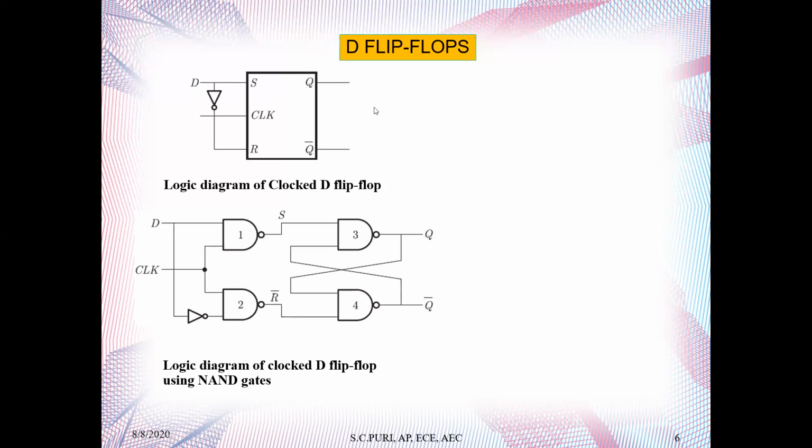So what is the advantage? Delay. The advantage is the delay. Using this configuration, we can introduce a timing delay, and this timing delay will be simply equal to the propagation delay. So if you give input here, after this delay, that means when you give input and you get output, it goes through all the gates over here. Every gate from input to output has a delay. So upon this whole delay, you get what is called propagation delay.